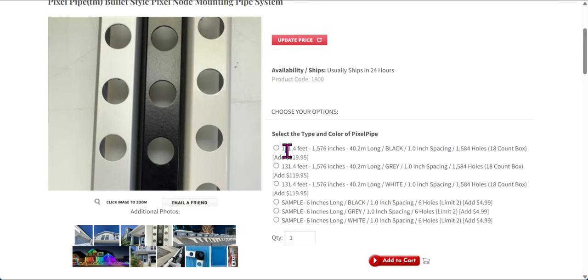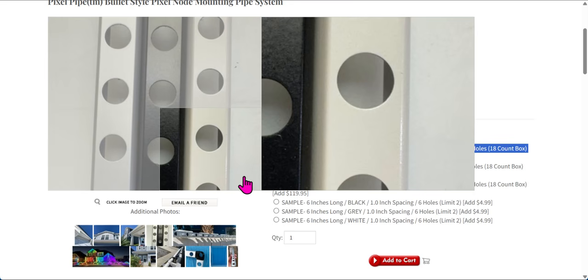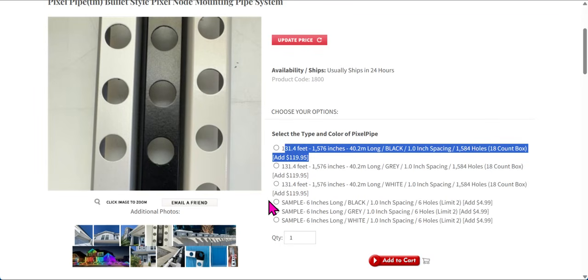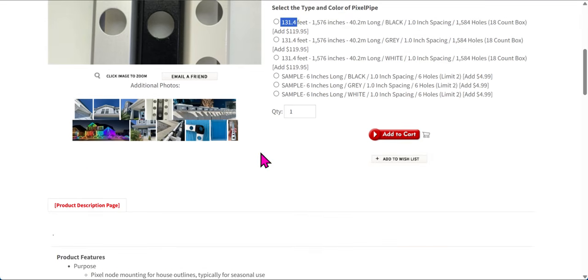So I do recommend when you're purchasing this, because with any of these projects, they're all customized. If you're using a window, and let's say your window is 66 inches and you're starting with an 89-inch piece, you may cut that down and get down to a part that is not really usable for another section of your house. So go ahead, and I recommend ordering an extra 10%. So if you have 100 feet, great, you're going to be okay. You got extra space in there. But if you need more than 131 feet, add in that percentage.